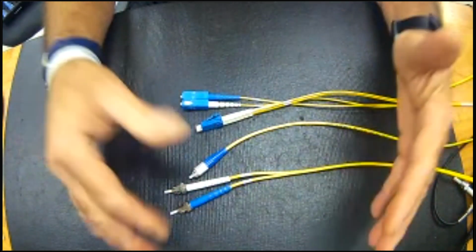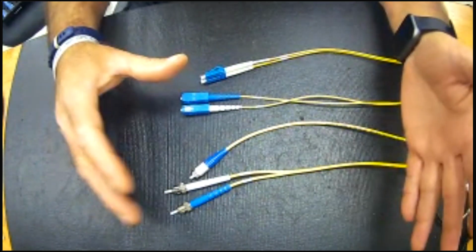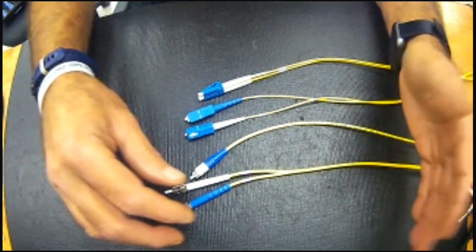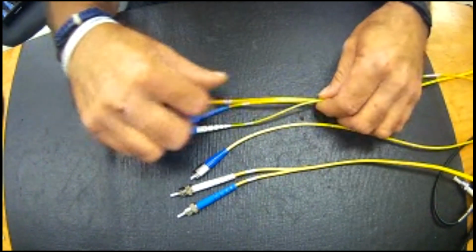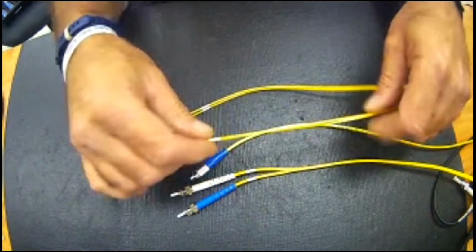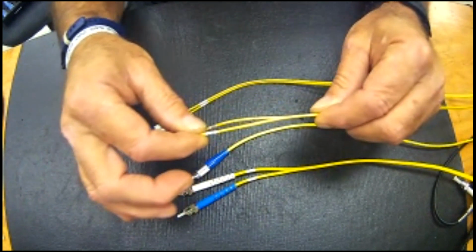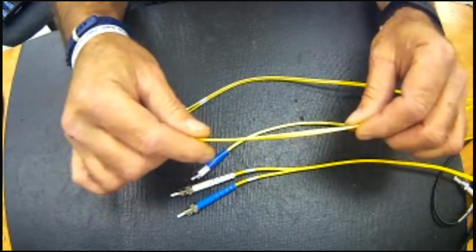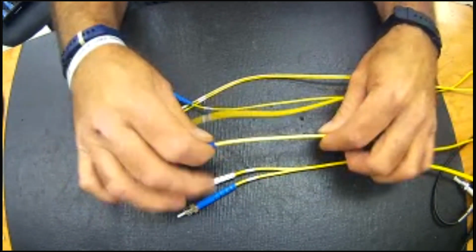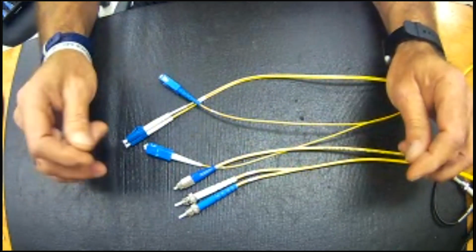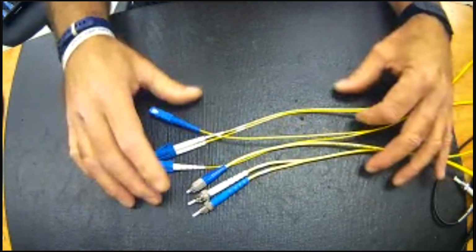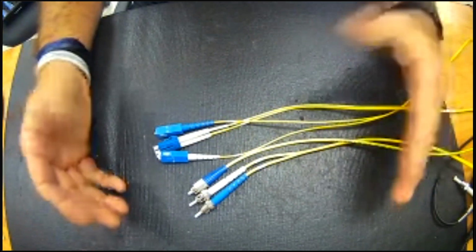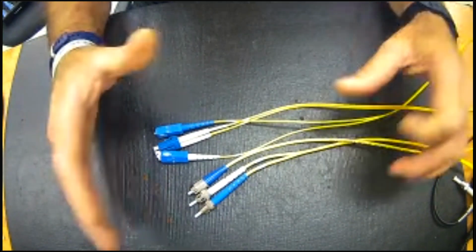Commonly, patch cords are just standard PVC. They're not tactical. You can purchase custom tactical patch cords, but that's not your bread and butter. So, knowing what diameter you would like and why you would like it, I would not use a 1.8 millimeter diameter jacketed fiber in the field. It's not going to last a minute if it gets slammed or caught on anything. Whereas a 3 millimeter is going to hold up much better. Now, knowing what you want is very important, and knowing its application, where you intend to use it. That's really up to the engineering staff, not up to purchasing.